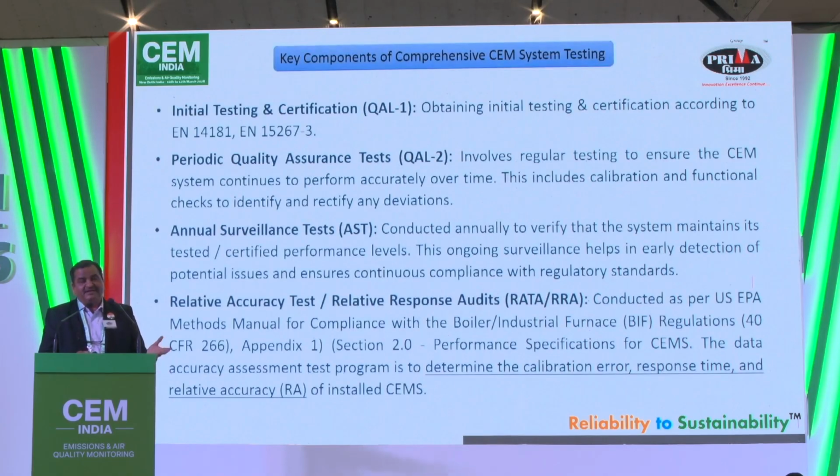So what are the key components of comprehensive CEMS testing? Initial testing and certification, that's QAL 1, as per 14181 and 15267-3. Periodic quality assurance test, QAL 2, which we don't do in India.